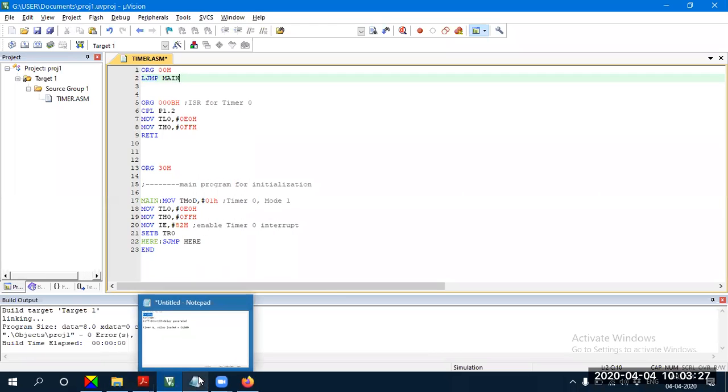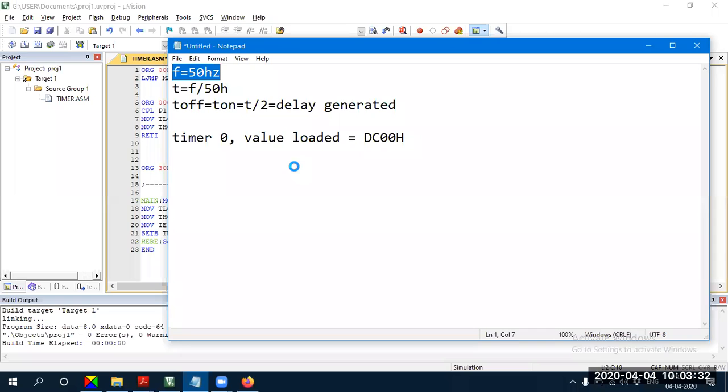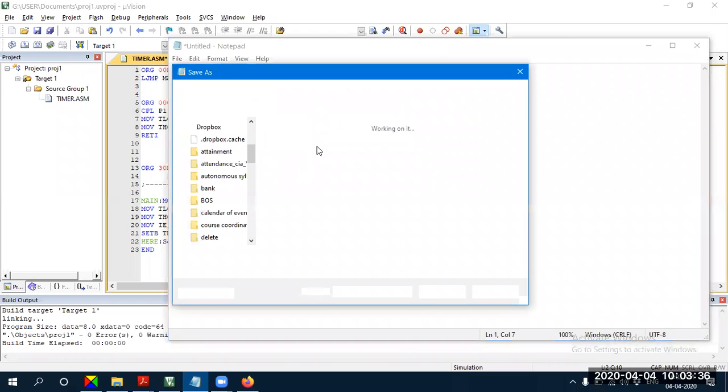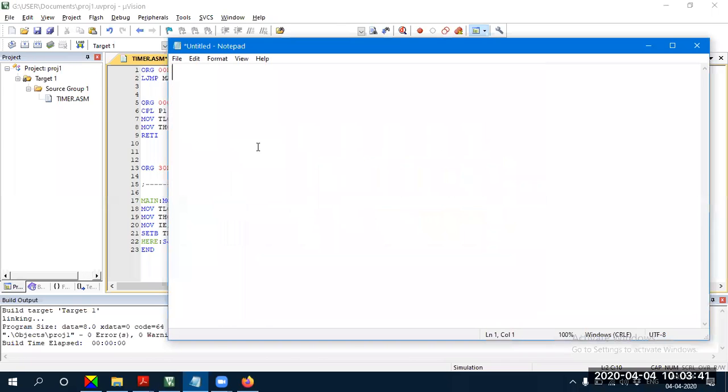The way we take a main is because of the addresses for the interrupt service routine. For the ISR, the addresses are allotted in the internal ROM space. To start with, for the reset pin, the address starts from 0000. Then for external interrupt 1.